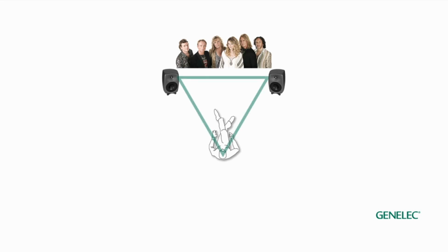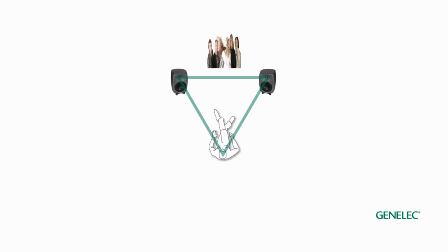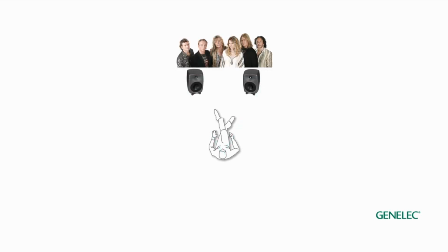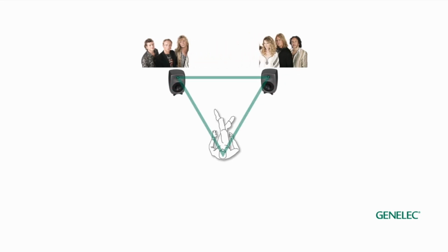If mixing happens with the monitors having been placed too wide, then when final listening happens in the standard setup, all the images will not spread out in the way that you originally intended in the studio. The audio presentation at the reproduction end appears to be too narrow and crammed in the middle. If mixing happens with the monitors placed too narrow, then the soundstage engineered in the studio can appear to stretch out at home and lose the normal structure in the middle.